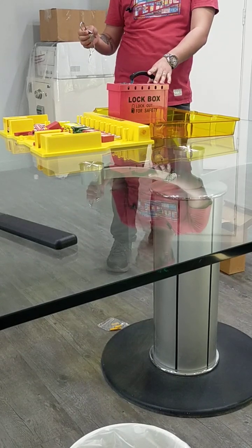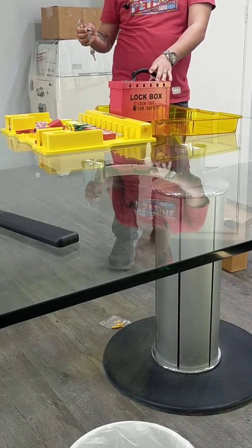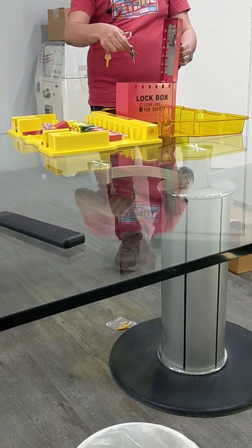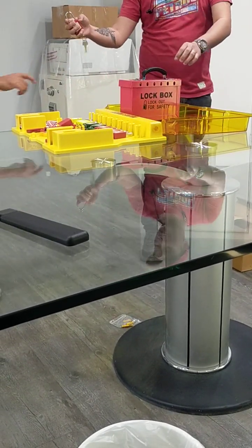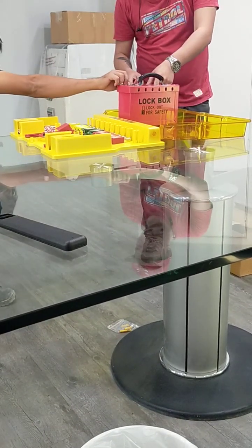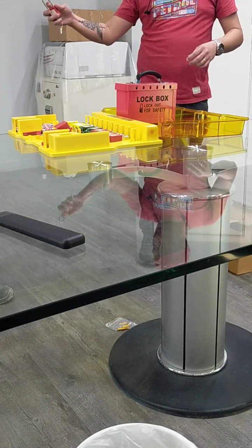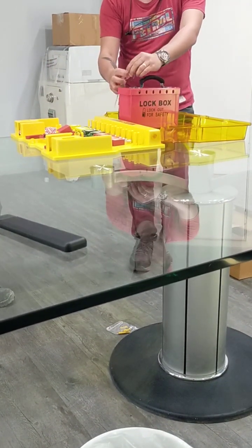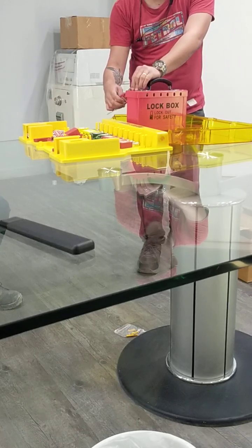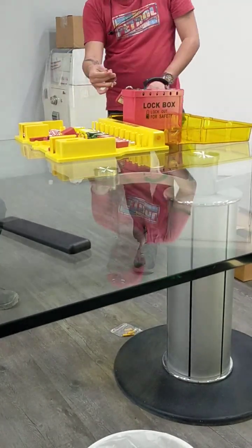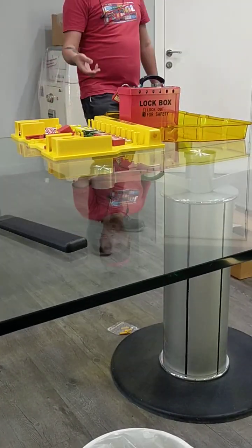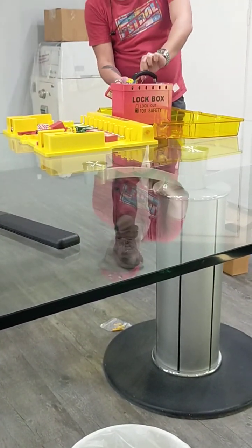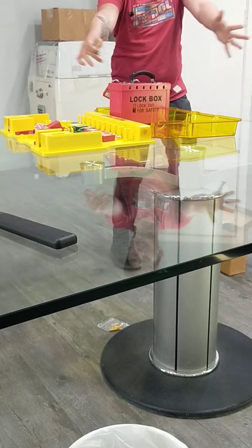See, you will not use your own padlock in the breaker. We will be having the group lock. For example, not the padlock. So the group lock will be placed here. And this is your key. You will lock using your own. For example, this is your key. You put here. This is yours. I go lunch. You go lunch. My padlock is here. For example, this is mine and everybody's padlock is there.